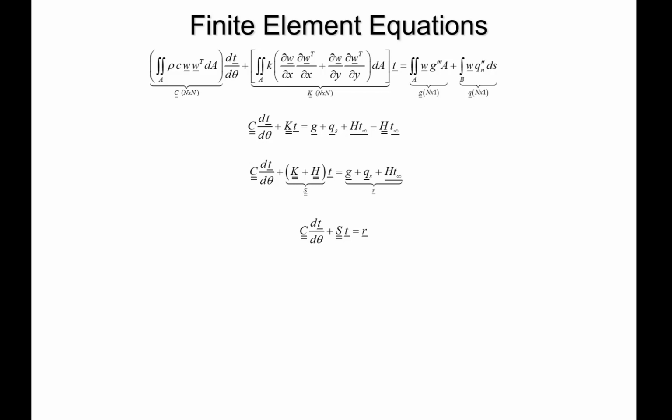So as we move forward, the next thing we have to talk about is how you take a mesh, how you take the information that would specify a mesh, which is going to be put into a very specific format. It's going to have to do with what points specify the nodes, and then how they're connected to specify elements, and then how they're connected to make boundary segments. And that information you would get from any kind of a mesh generator. But how you take that information and then use it in a very prescribed way to get these different matrices and vectors that we have listed here.